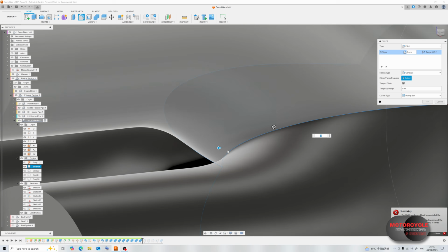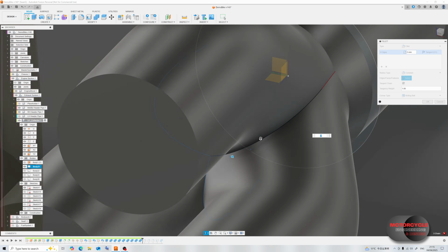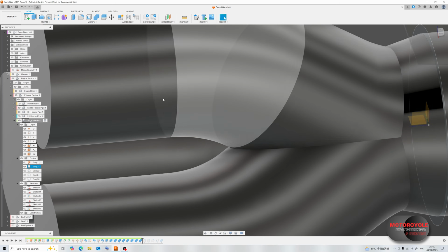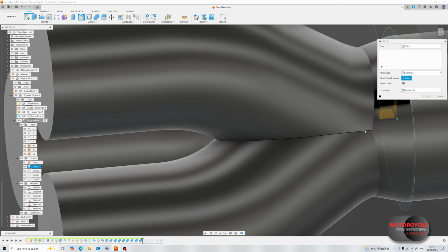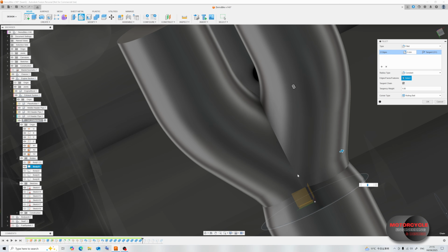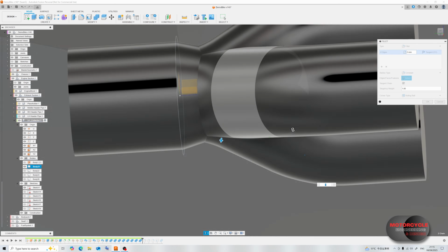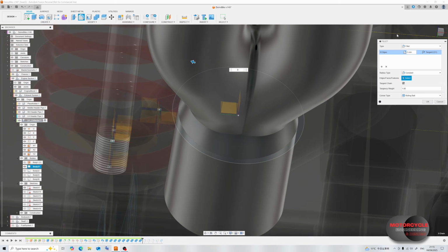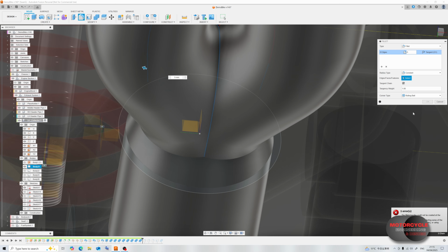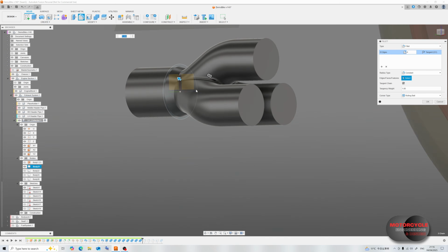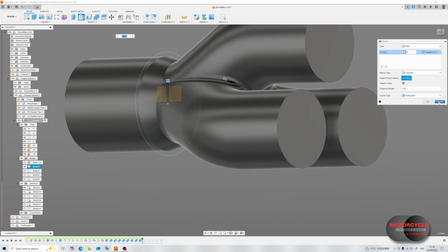So for some reason, if we select the top, maybe it's the angle at which we're looking, it doesn't like it. So what I found was when I was placing my rounds, if I always select the bottom, I never had a problem. You get all 3 of them in, no problem. And I wanted to boost those up as large as possible, because we will be reducing the material thickness here, and that allows us to have slightly thicker walls.